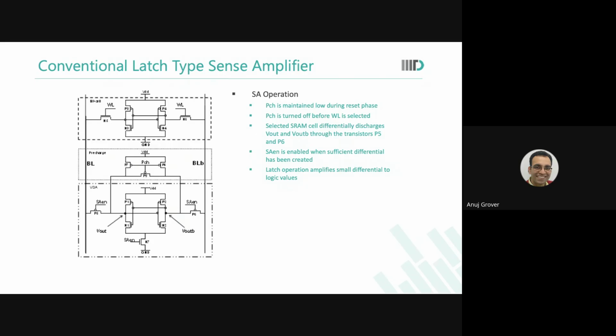It would be same variation across both. So whichever place my die is on the wafer, I don't need to bother now. See, can you change the design from this part of the wafer to that part of the wafer? No. The same mask, it will scan the entire wafer in the same way. But you will start to observe yield loss in this ring because of these variations coming in. You don't want that. So what you say is, I will do common centroid layout. Now, schematic doesn't make a difference. Finally, what goes on silicon is the layout. Schematic में आप कुछ भी दिखा लो, it will always assume common centroid.